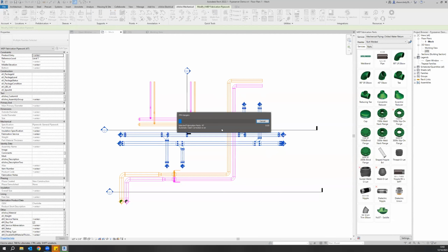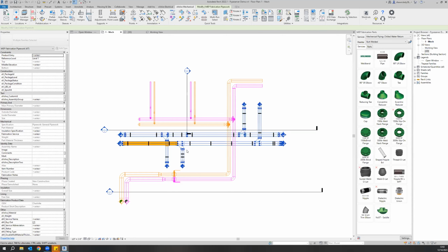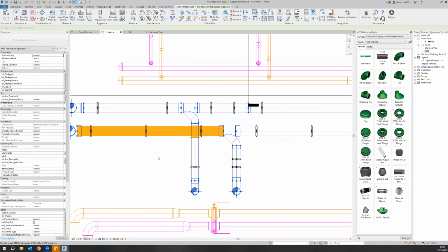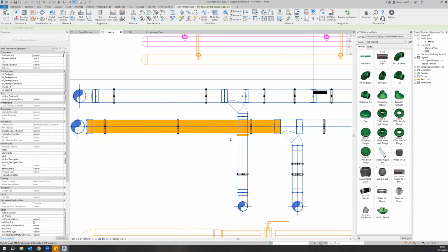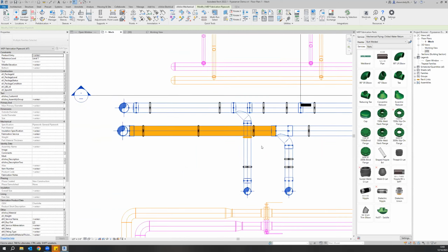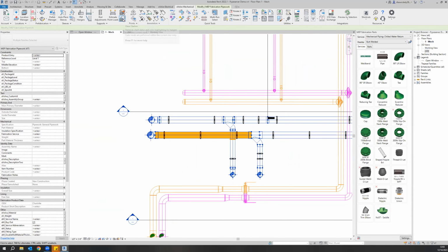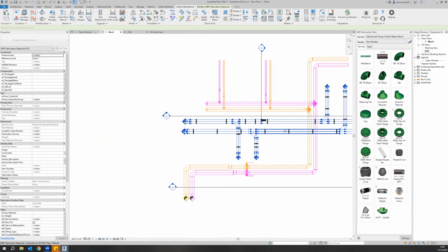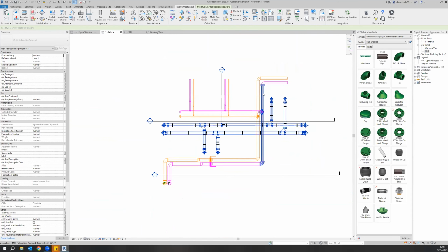One nice thing about the ITM hangers is they go on pretty quick. They do automatic clash detection, and we have different settings for the space around the hangers or around the items that will throw up a clash. In this case, I have my tolerance set to 2 inches. I have it set to within a foot of this connector, and it's within 2 inches of this other pipe, so it's telling us we have a clash. That's how the clash detection works for any other items in the model. If you have duct and everything, it'll clash around other links as well.